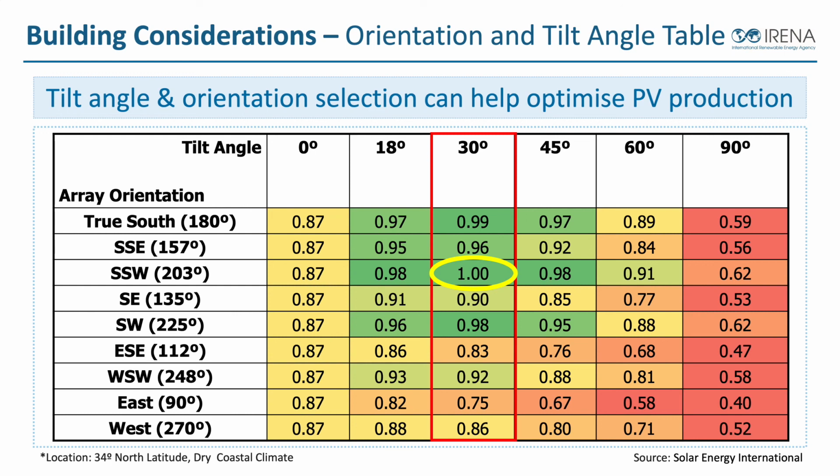The only reason there's little differences sometimes there in southeast or southwest in energy production would be because of local weather patterns. When we get into designing systems and utilizing some various programs and software modeling, we can model based on the location and historical weather patterns what amount of power and energy should be produced from our solar array given the latitude, longitude, local historical weather and the array tilt and orientation. So it can all be calculated.